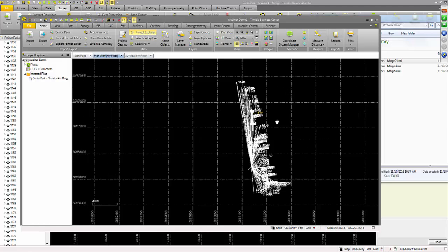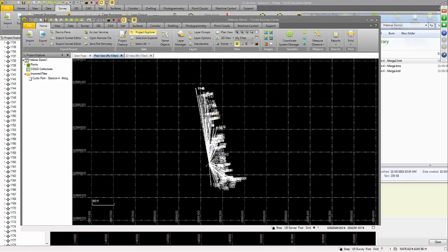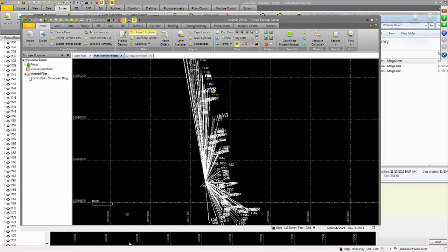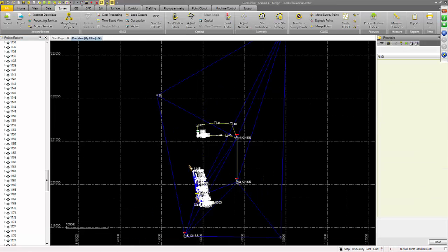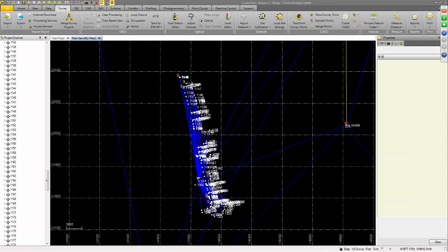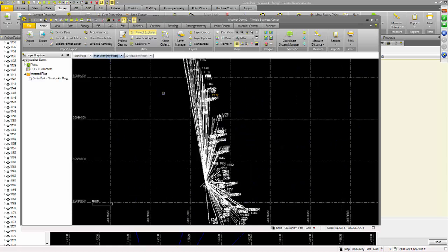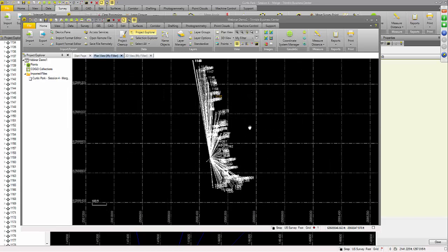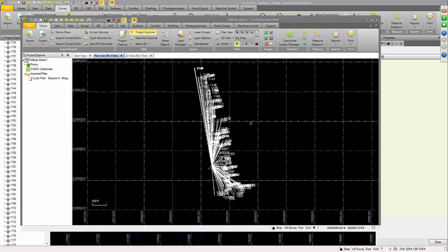So this data right here that I'm using is created in an export from this other project. So I took my RTK data here, exported it as a KML, and then imported it into a fresh TBC project. So just a test, you can experiment with different data types, but anything that you're saving as a KML.